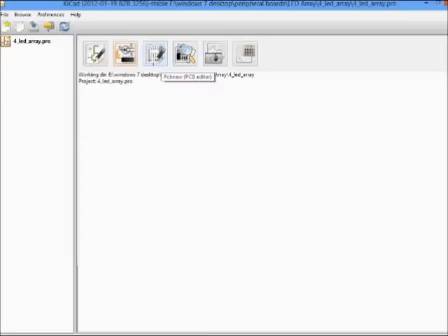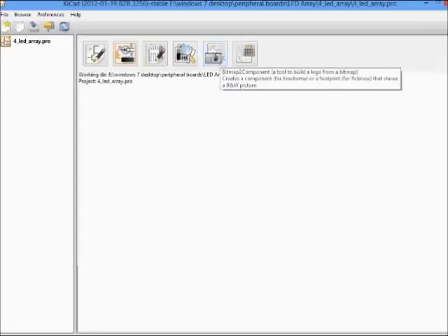This is where you draw the layout of the PCB. And then again, if you generate Gerbers from KiCad or any other software, basically Gerbers are the final files that are sent for fabrication, and if you have done those, you can view it using the Gerb view. So Gerbers are industry standard, and Gerbers generated by any other software or KiCad itself can be seen with this. Now this is another interesting tool, and this is to create a logo out of an image.